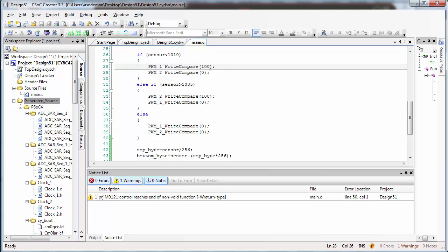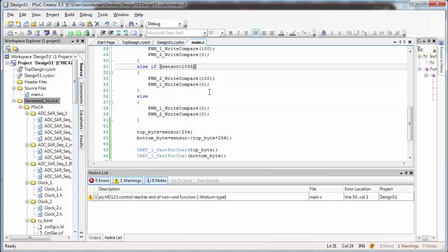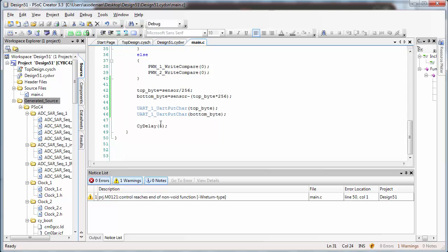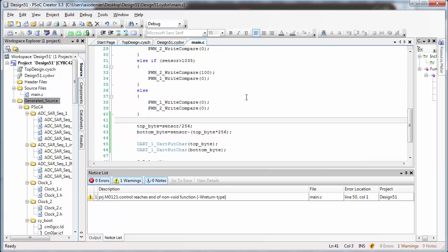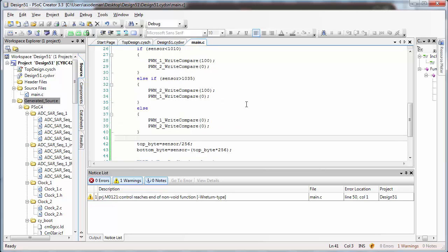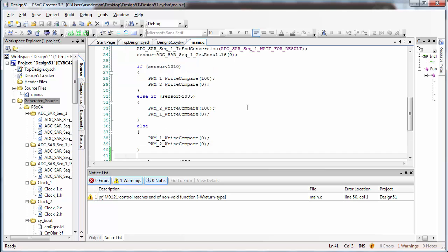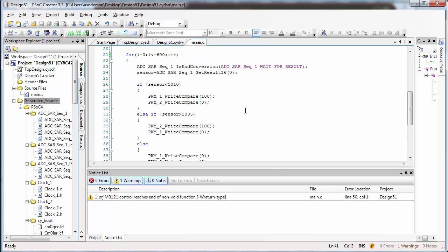So either change the speed, or change the buffer around which we have the motor stop, or change this delay time. And then I want you to run the experiment again and calculate the overshoot, the steady state error, the settling time, and the rise time with your new change.